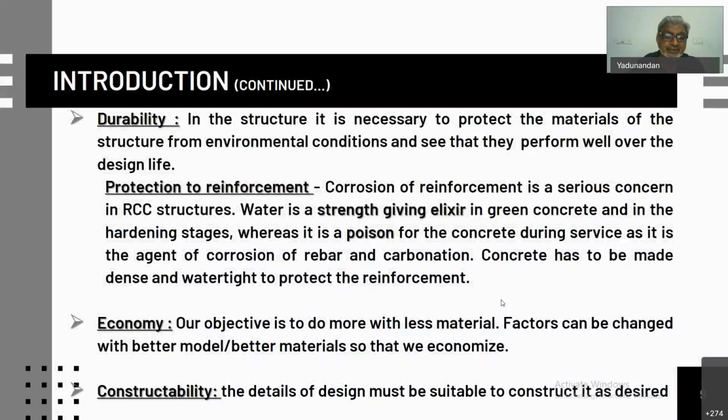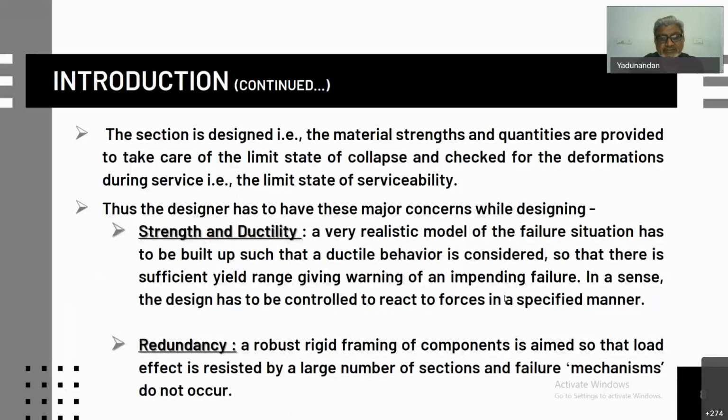And of course, it is not sufficient that if one section is designed that way, we are trying to see or make a structure in such a way that we build in redundancy to the structure. We build a robust, rigid framing of components so that load effect is resisted by a large number of sections and failure mechanisms which cause the collapse of the structure do not occur.